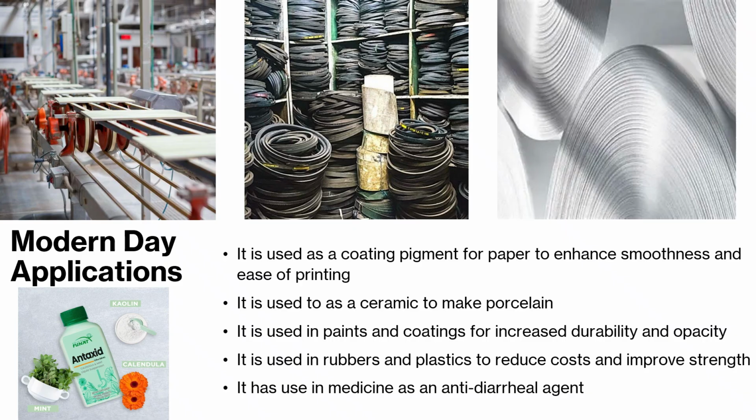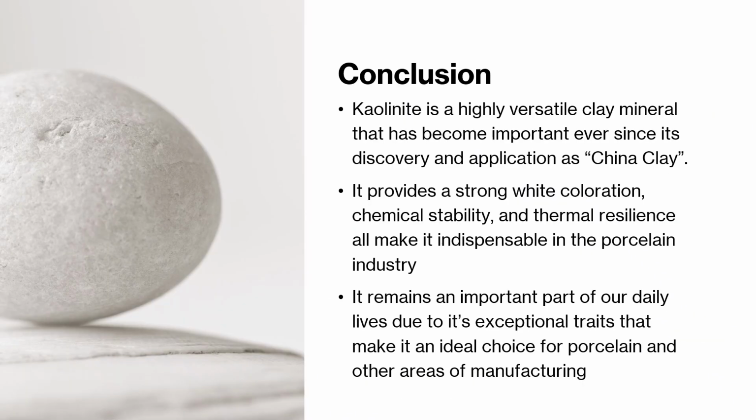In conclusion, kaolinite may seem like a simple clay, but from its formation to its manufacture, it's an interesting and long process. From chemical weathering in only specific regions to being excavated through heavy machinery and then refined through steps like plunging, screening, and drying, magnetic separation, you end up going from just some dirt to an extremely useful and versatile material.